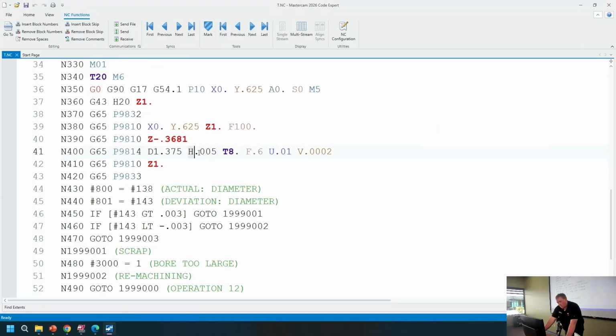You'll notice there's a couple extra inputs here to the macro. Here's where I'm actually copying in that data, right? So Renishaw is writing into these common variables, and those are being overwritten per probing cycle. So by copying that into a user-defined variable, it's going to stay there so you can reference that data later, use it in the calculation, whatever you may need to do.